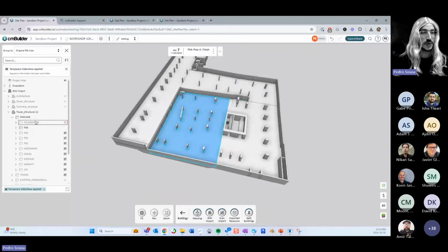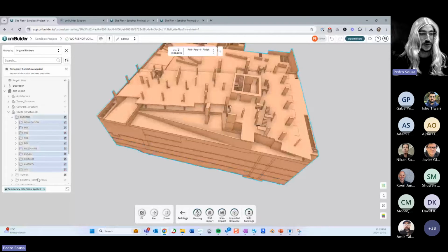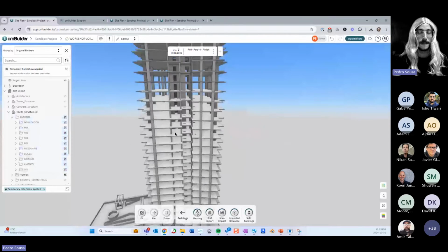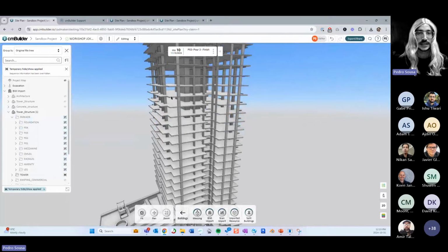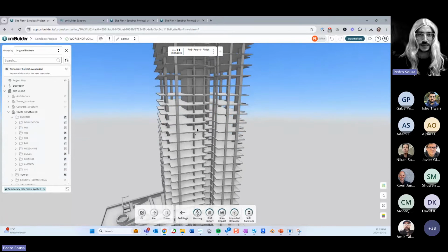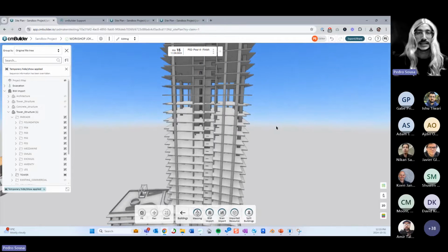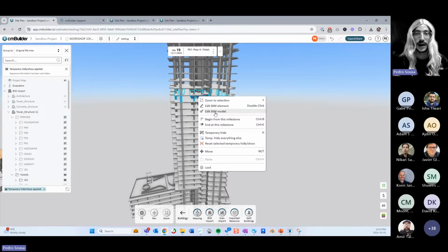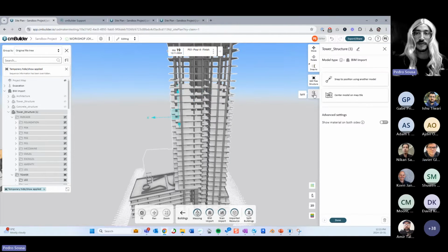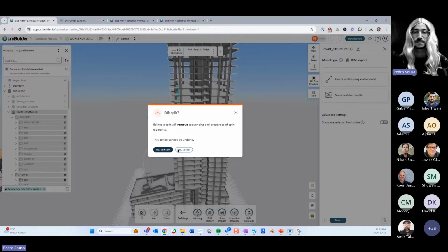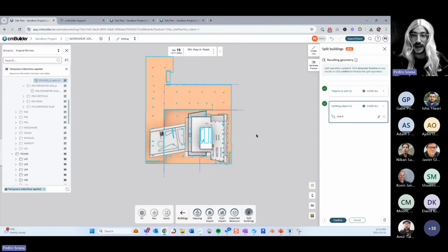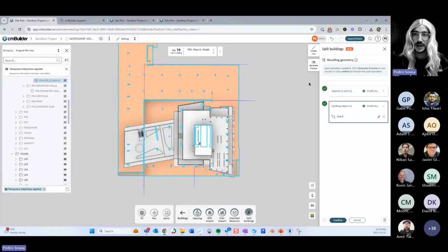So let's do a similar thing, but now using the tower structure. For the tower structure, if I wanted to combine these 4 breaks and these slabs and create a huge pour break for all of these slabs, I can simply go in and create a split, sorry, with the parts that I already created, and create a second sketch, right?